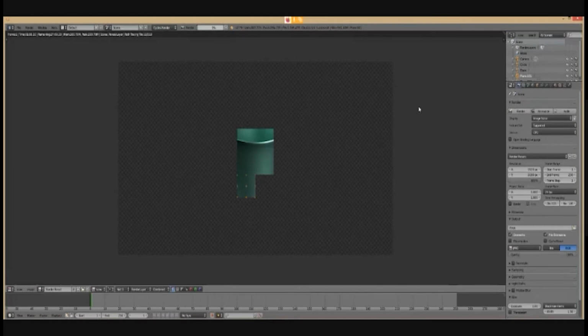For example, if you want to perform a loop cut on a particular surface, you click on any point on that surface. For example, you can click on an edge or a face. Once you click on, let's say, an edge or face, and you press Control plus R, you will notice that a purple line, or a purple enclosure, comes.